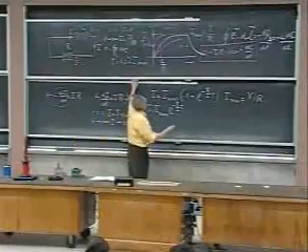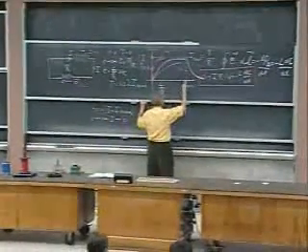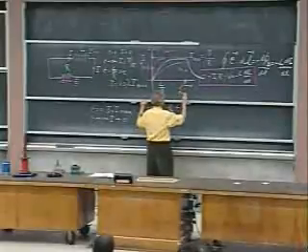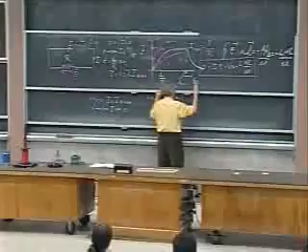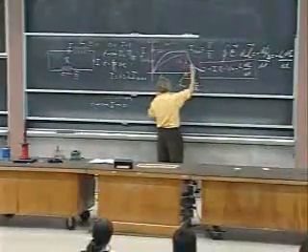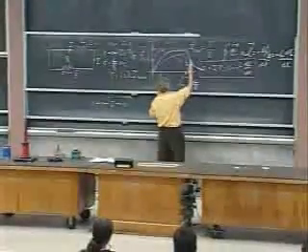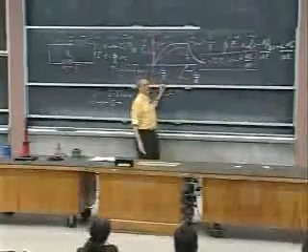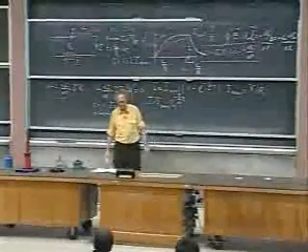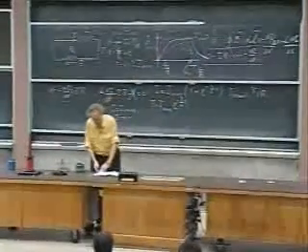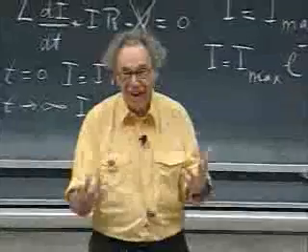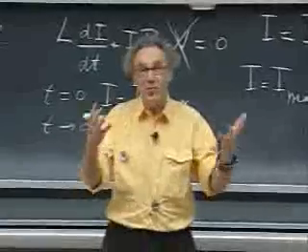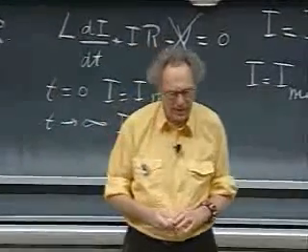So if you now go, I redefine t equals 0 here. So if now I wait L over R seconds, then this value here is about 37% of that value. So you've lost 63%. And so you see this is the consequence of the fact that the circuit is capable of fighting its own magnetic flux that it is creating.